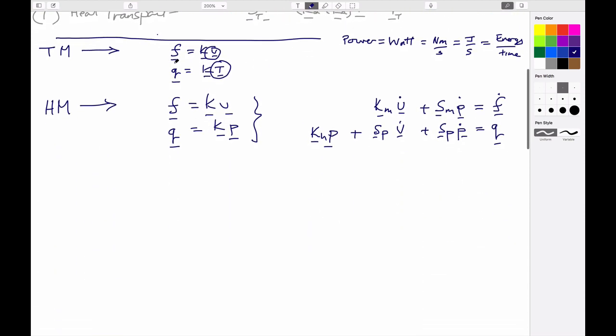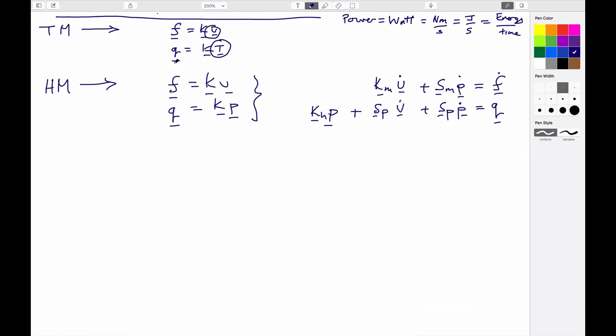And so if we think about what these terms are exactly, then what are they? So this is just the straight mechanical part that allows it to deform without the influence of fluid in it. This is the straight flow part that allows flow to occur and it doesn't care about any deformation. This is the part that is due to the rate of change, the compressibility of the fluid.